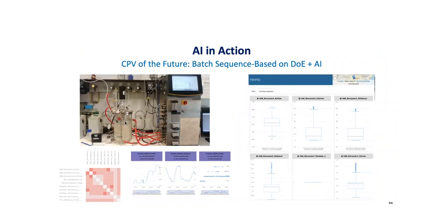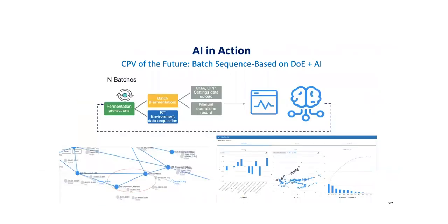Well, we put all the sensors in this bioreactor, a 5 liter bioreactor, and we tried to figure out which factors were the most important. We applied design of experiments and we applied AI. The first thing that we did was to identify the variables that were explaining the real problem. So not everything is always needed. Sometimes you need only those variables that are the most relevant to explain the problem. Taking these variables and defining which of them explain the problem, you can create models, and we created 1 model per hour, and the fermentation required 24 hours. So we had 24 models, 1 per hour.